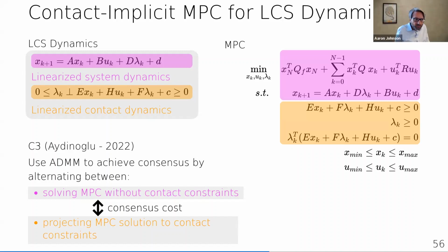All right. And then in terms of this step, especially with frictional sliding, there are infinitely many ways you could project onto feasible contact dynamics. Is there any trickiness with how you do that projection? Yes, there are infinitely many ways, and there's also a choice in how you construct the LCS. How do we find the lambda, and how do we get these contact boundaries? There are a lot of ways to write a discrete time-stepping contact model. For this work specifically, we use an Anitescu model, which linearizes the friction cone to just 4 directions. That's how you get around the infinite sliding directions. Although it can support more, 4 seem to be enough.